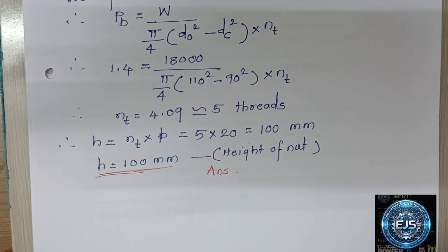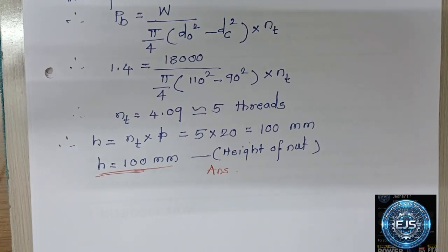प्रॉब्लम का सोल्यूशन थोड़ा लंबा है, लेकिन स्टेप बाय स्टेप उसको कैलकुलेट करना है. पहले टोटल टॉर्क कैलकुलेट करना है. टोटल टॉर्क से मैकेनिकल एफिशिएंसी का फॉर्मूला यूज करके T अपॉन मैकेनिकल एफिशिएंसी इक्वल टू टोटल टॉर्क अपॉन टॉर्क एक्टिंग ऑन गियर व्हील T अपॉन TG. फिर गियर रेशो का फॉर्मूला है TG अपॉन TP. वहां से हमें TP का इक्वेशन फाइंड आउट करना है, वो टॉर्क कैलकुलेट करना है, टॉर्क एक्टिंग ऑन पिनियन शाफ्ट.